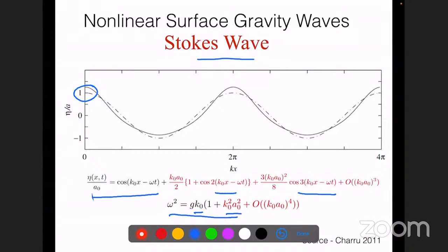And this, if you remember again from the first lecture, we worked out the frequency for a simple pendulum, √(g/L), where I have a single degree of freedom and the frequency is √(g/L). And there, if you were careful, you would have noticed that I made the small angle approximation. I said that in the governing equation for the pendulum, sin θ is approximated as θ.